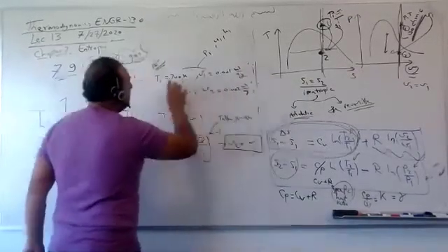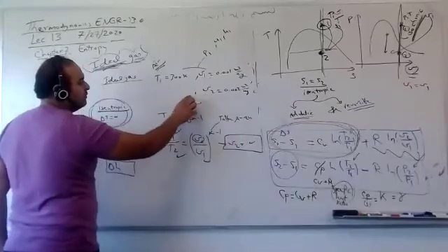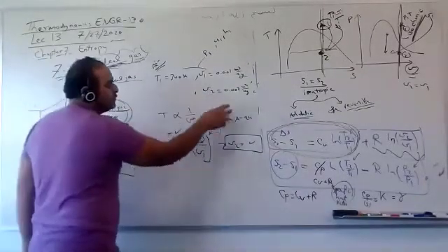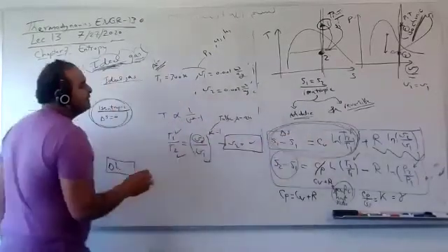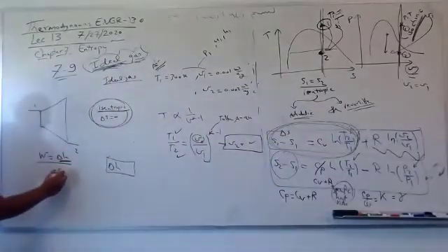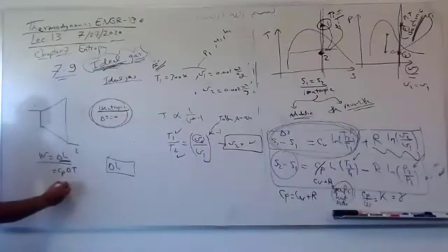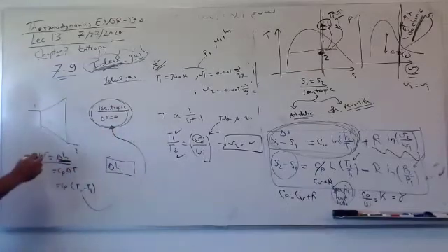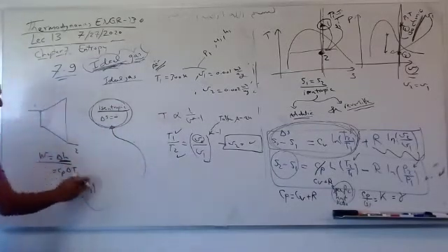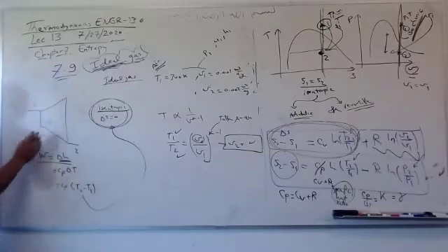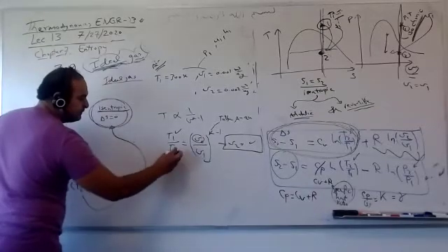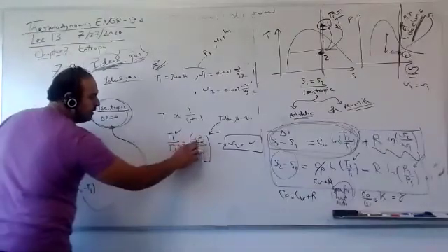Let's say you have T1, V1, V2, but I said isentropic. So you have V1 over V2, and we can get T2. So this guy, just Cp delta T. So I wish to have T2. The only way is through isentropic. To obtain delta H, we need delta T, because it's an ideal gas. Let's say air. Cp is given, T1 is given, T2 I don't know. So from where can I get T2? From this correlation.